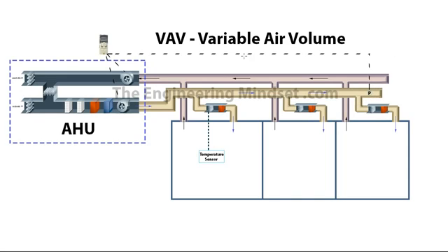And these are connected over to the VSD, the variable speed drive or the variable frequency drive. The VFD is connected directly to the fans, the fan motors, and the VFD will then slow the fans down, slow the induction motors down, and this will reduce the amount of air being pushed into the duct. The pressure sensor is set with a set point of where it should be operating at, or what that pressure should be at that end of the duct, and the fans will reduce in speed to reduce the amount of air being pushed into there to match that pressure point.